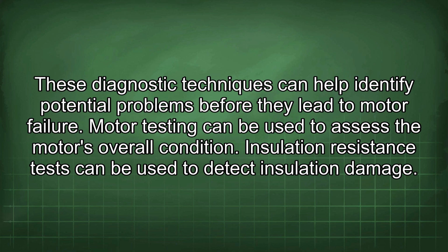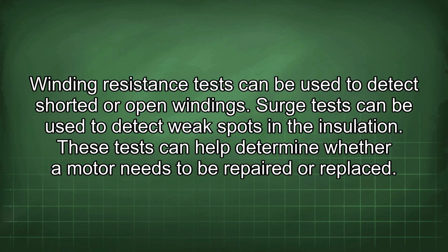Motor testing can be used to assess the motor's overall condition. Insulation resistance tests can be used to detect insulation damage. Winding resistance tests can be used to detect shorted or open windings. Surge tests can be used to detect weak spots in the insulation. These tests can help determine whether a motor needs to be repaired or replaced.